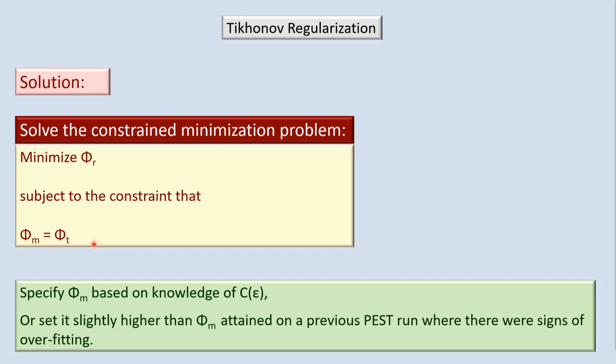We can use Tikhonov regularization to get as good a fit as possible in ways that are available through PEST. For example, I can tell PEST to set the target measurement objective function always at about, for example, 10% of the current measurement objective function. That'll be discussed in another video. And I can get a pretty good solution to that inverse problem through doing that, but the fit will probably still be too good and the parameter field probably a little bit too rough because of that.